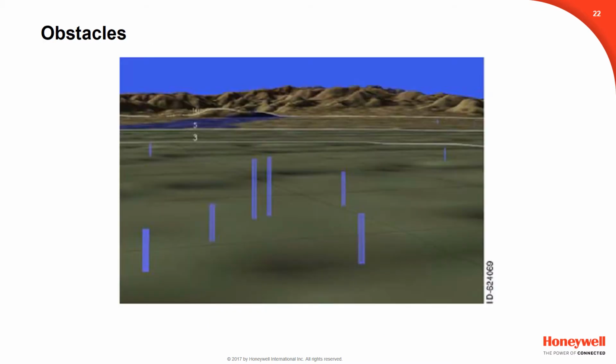All reported obstacles in the terrain view taller than 200 feet are shown on the display as blue images. Obstacles are centered at their respective latitude and longitude and are drawn to their published height. The width and depth of the obstacles are fixed at 100 feet. SVS obstacles begin to fade into view at 40 nautical miles and are fully in view at 27.5 nautical miles. Obstacles that are closer to the aircraft position appear larger than those that are further away.